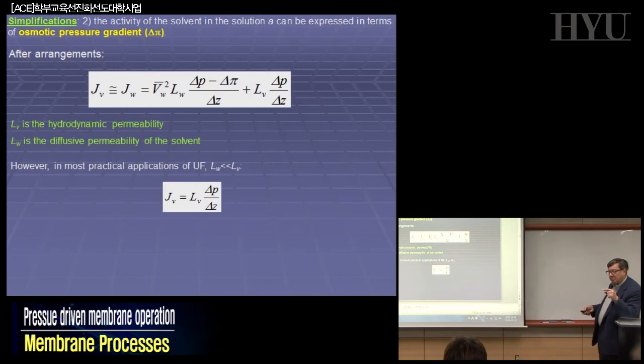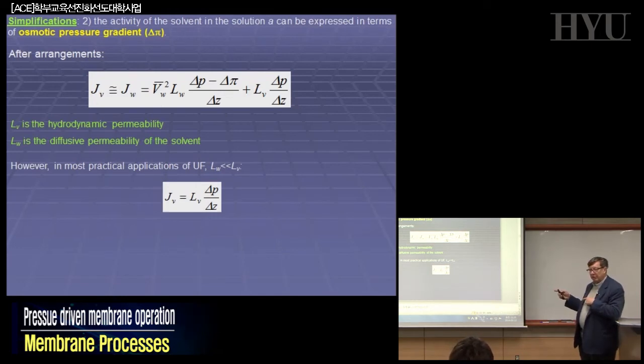Remember that some industrial membranes, in the 80s, 90s, were called dynamically formed membranes. They were ultrafiltration membranes, or sometimes microfiltration membranes, on which, on purpose, you can induce the formation during the operation. For example, in the textile industry, during the operation, you can form a deposition of some chemicals which are inducing osmotic phenomena, dynamically formed ultrafiltration membranes. So these membranes have a rejection for the dyes in the textile industry.